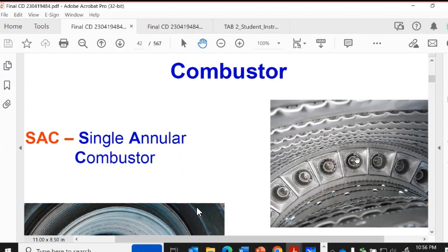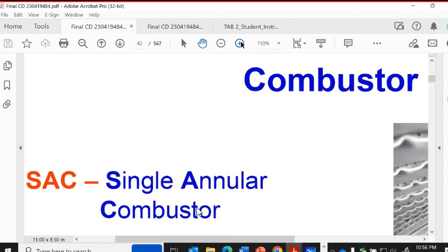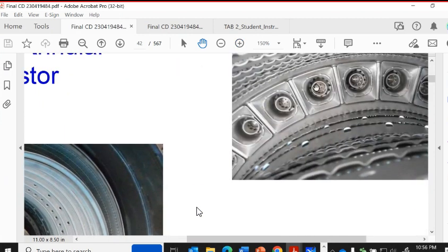This is something that's more susceptible to liquid fuel. Liquid fuel has a tendency to coat the nozzles and sometimes plug the orifice holes. You can see the small holes. These small holes are where the fuel is coming out through here. And liquid fuel has a tendency sometimes with the hot surfaces, if it's still wet after it's shut down, the liquid fuel kind of dries on here, starts causing coking to form, and that causes a deflection in the flame pattern through here.